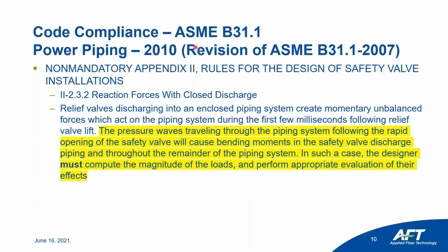Continuing with B31.1, the non-mandatory Appendix 2, rules for design of safety valve installation. This Appendix 2 addresses two types of discharges for relief valve. One is for relieving to atmosphere, an open system, but in that case, it has a very good guidance on how to calculate the reaction forces.